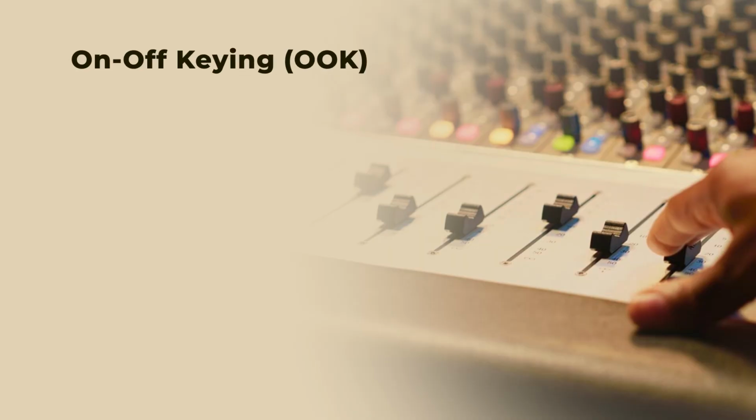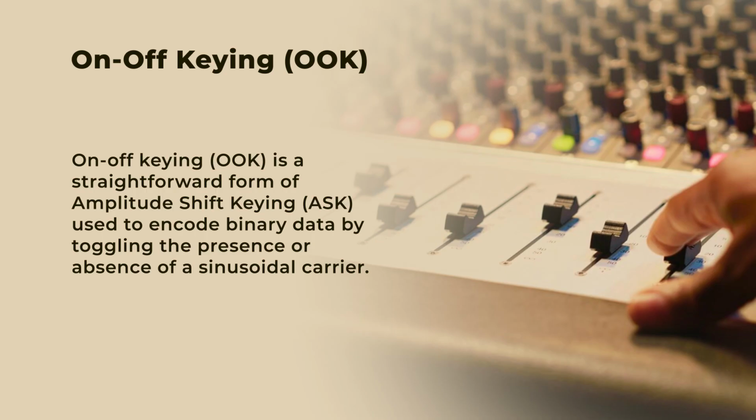The next topic is on-off keying, that is OOK. On-off keying is a straightforward form of amplitude shift keying used to encode binary data by toggling the presence or absence of the sinusoidal carrier. For instance, during a bit duration TB, the presence of the carrier can represent a binary 1, while the absence can signify a binary 0.